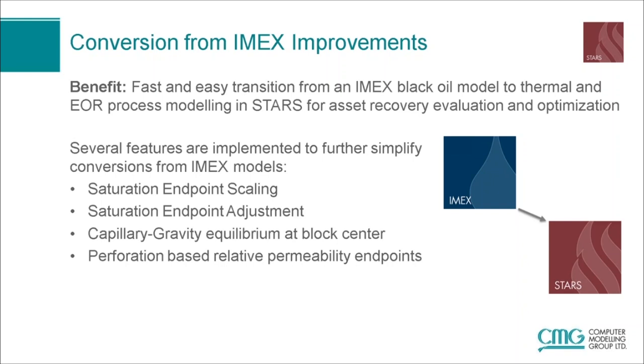One of the ways is we have a builder process wizard that will automatically convert all of the IMEX keywords in PVT into STARS PVT and keywords for you. And we've now streamlined the conversion process even further by making it easier to get an exact match between the two simulators. And this was done by aligning several options, mostly related to relative permeability between IMEX and STARS.